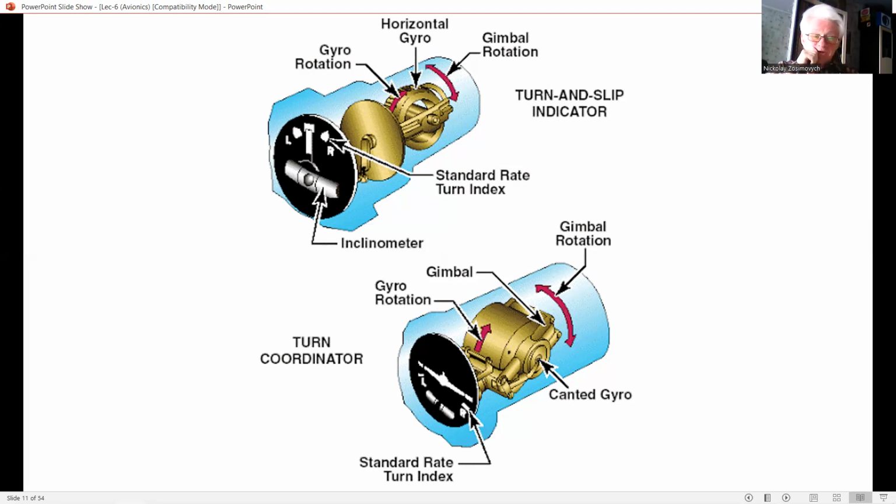It should be noted that while airstream incidence sensors can also provide the stabilizing term to counter the unstable M sub alpha, they have two inherent shortcomings as far as the core stabilizing function is concerned. And in this case, we have several conditions.